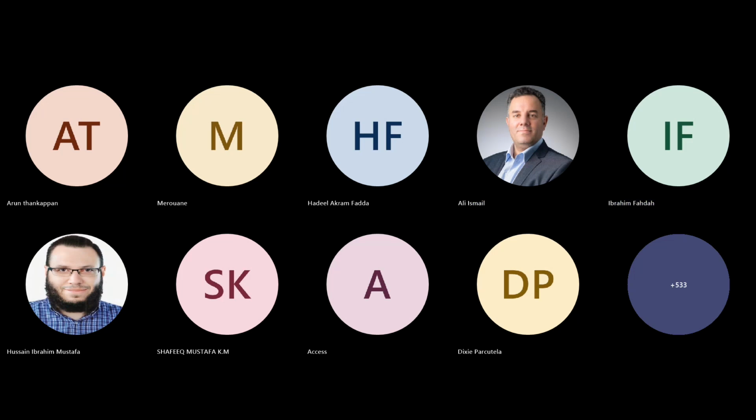Regarding the question about overriding internal walls, there is an attribute for all walls indicating whether the wall is external or internal, so no need to override it. You just have to set this parameter, internal or external.